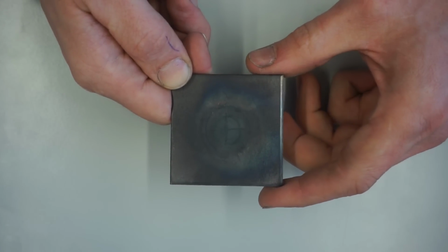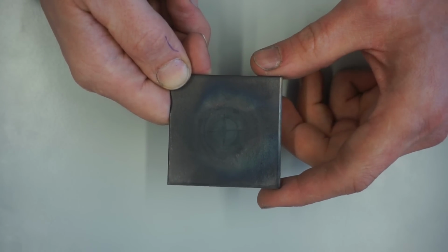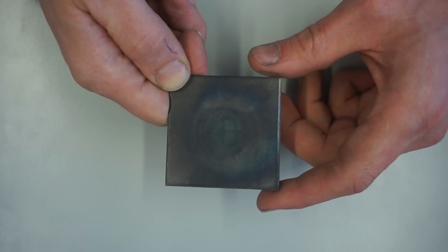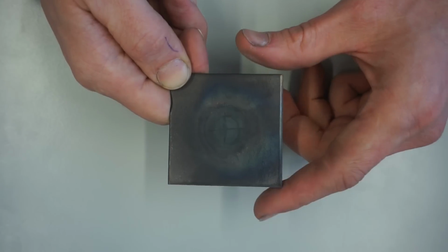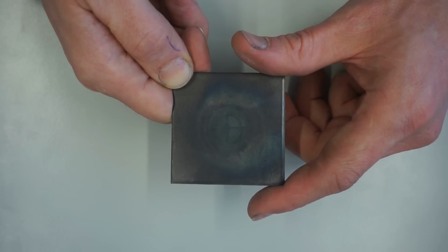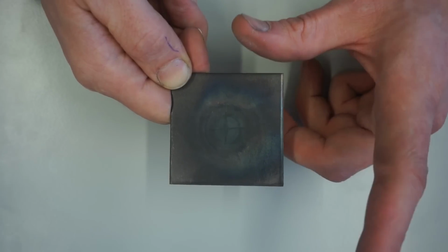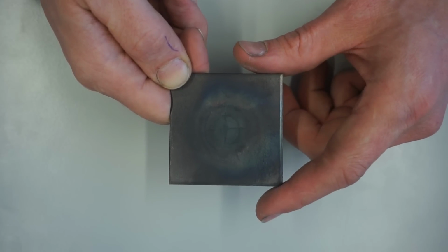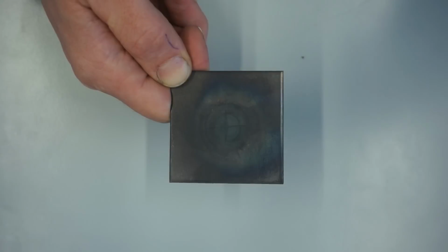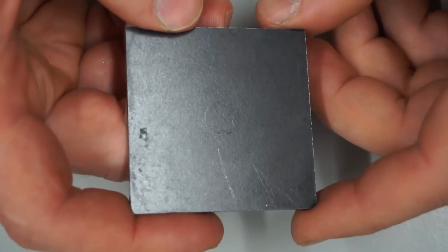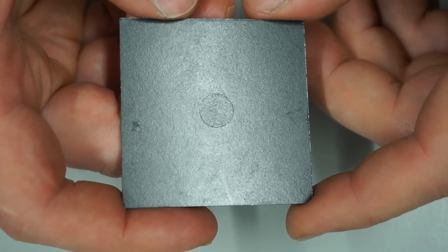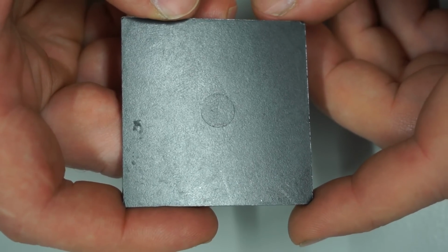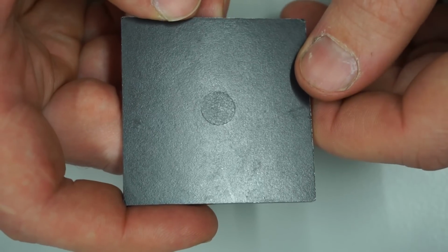A student of mine proposed a very good interpretation of this behavior when he said that it is like baking a cake. The cake rises in the oven because the cake tin constrains it radially. You may laugh, but this is pretty similar to what we observe here. This next experiment should highlight the rising cake explanation and give us an idea of the residual stresses that develop due to the heated spot.